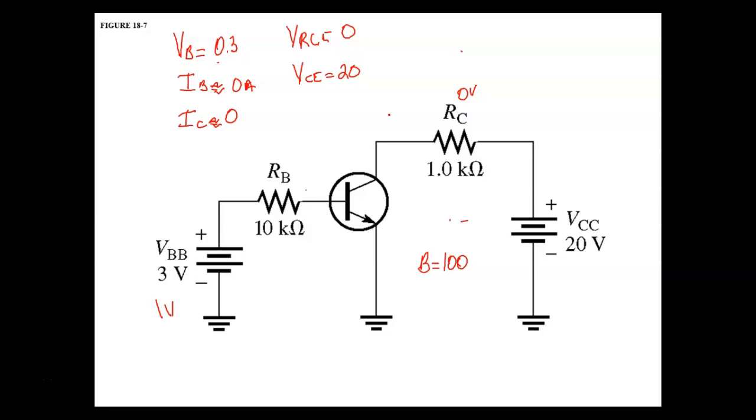So we'll look at the difference in the rating. The maximum current occurs at saturation. And then after that, when we're in the active region, we're going to be looking at the power the transistor can dissipate. So if you exceed the power rating, then the transistor is going to burn up too, right? So we'll look at some of those.